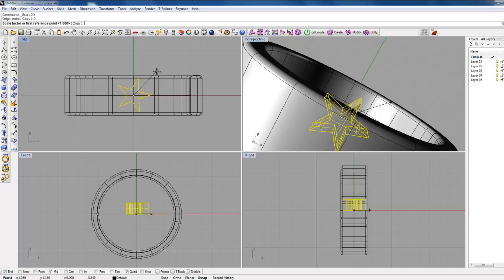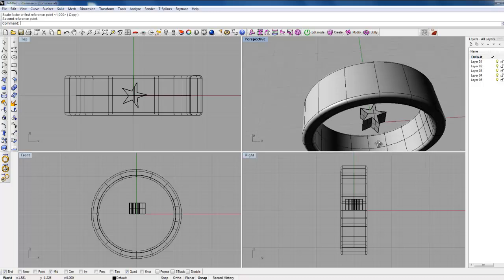So what we'll do is select 0, the origin point, from 0, enter, and then we'll just draw a line out there, and we'll push that line back with the mouse so it's a little bit smaller. There we go. So we'll scale that now. If you can see in there, it's got a little bit smaller.